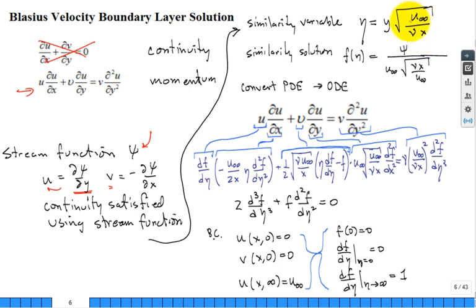What does that look like? Well, it looks like a Reynolds number in there, but let's not play with that right now. And then what we're interested in is a similarity solution, the function of eta, which is the stream function divided by U infinity square root nu x over U infinity. Okay, so using these you can convert the remaining PDE into an ODE. What? That's the trick in math. You know how to solve a simpler problem, so you make the more complex problem look like the simpler problem, then you solve it like you know how to solve the simpler problem.